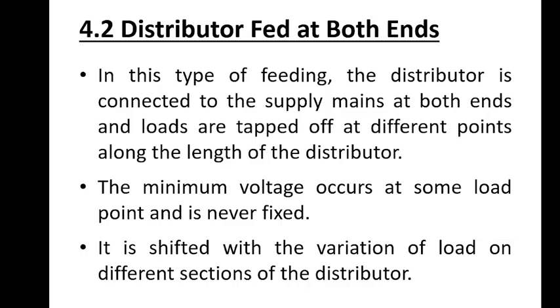And this minimum voltage point is not fixed and can shift as the load conditions change in different sections. So this type of feeding improves voltage regulation and reliability, making it a more efficient and flexible option for power distribution systems.